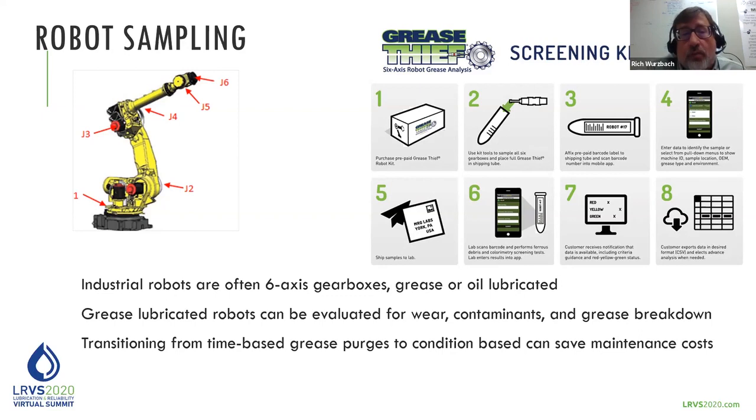And we compared the results of greases taken using one of these kits. What we found, and it wasn't always intuitive, was sometimes grease that was significantly oxidized or significantly subjected to shear stress, so that the consistency of the grease was changing. Sometimes it was on a heavier loaded robot. A lot of times it was on a short movement that happened frequently.